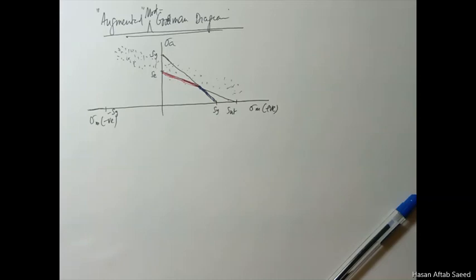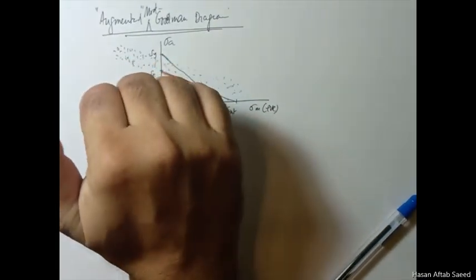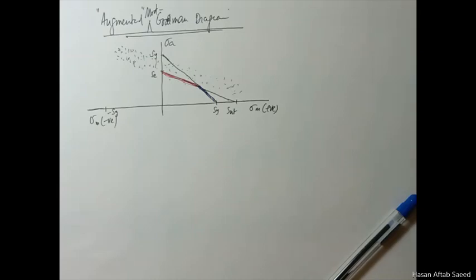So this whole thing takes place because of fatigue, tension and compression, but tension is the driving force. If you have a negative mean stress applied there, it tends to close the cracks, instead of opening them. So fatigue strength is increased by mean stress in the negative region.